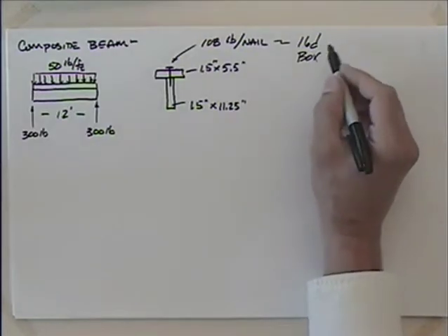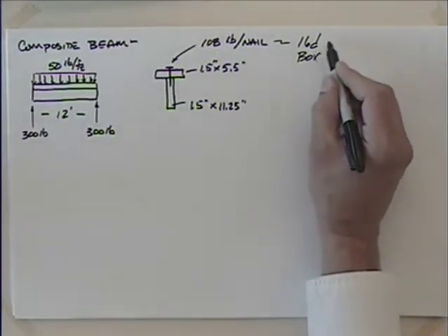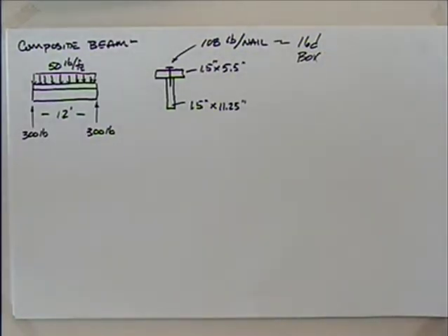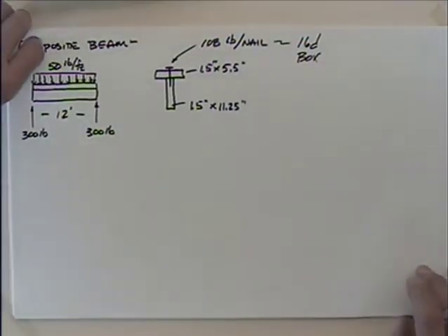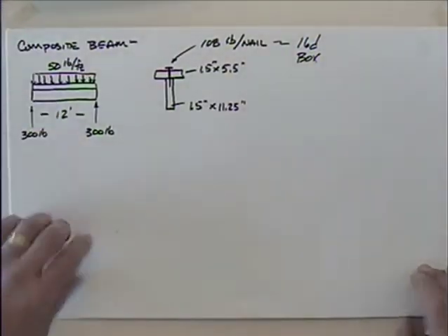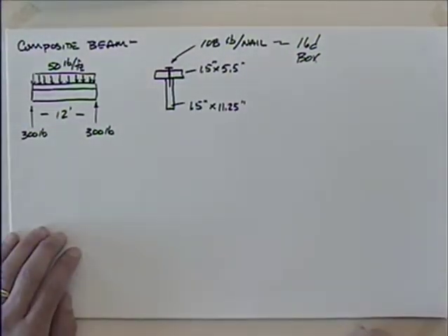This, call this a 16 penny nail, because that's kind of an antiquated term for English pennies for 100 nails. I think that's how that goes. A 16 penny nail is going to, I think, be about 3 1/4 inches in length. And the nail sizing goes up to 60D, which is about a 6-inch spike, and beyond that, usually they start just giving them with dimensions.